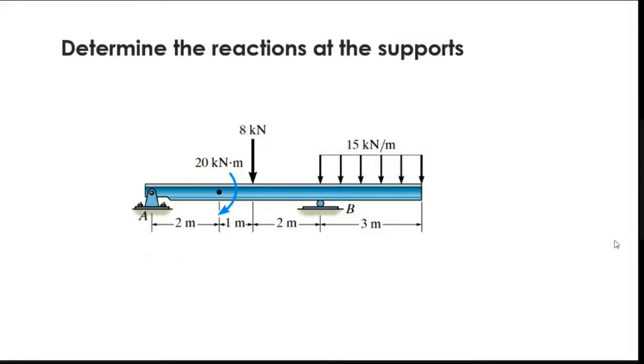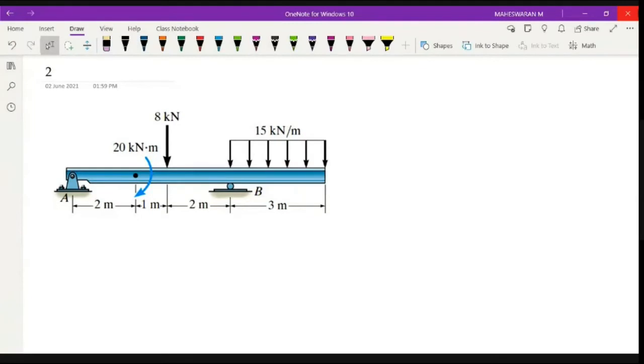Right. Now we will try to solve some problems related to these things. So what type of beam is this? Anyone? Where are the supports? At location A and location B. If your beam is up to B, then I can say it is simply supported. So it is extended, right? So it is a single-sided overhanging beam. Okay. Right. So now you have two supports, at A and at B.